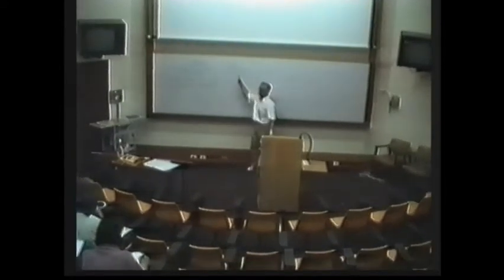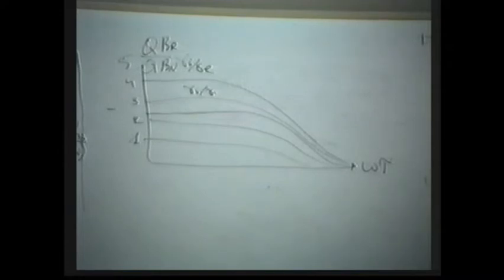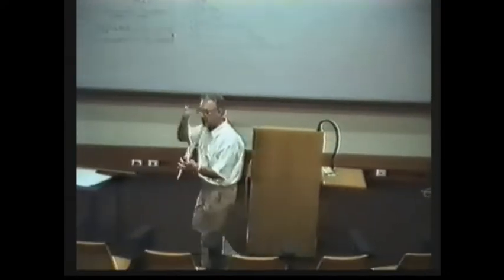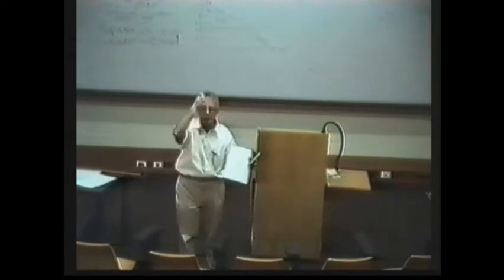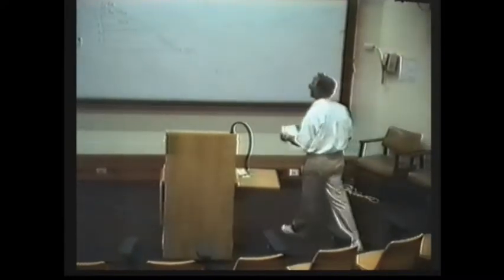So first of all, I hope it's clear that when we are at the low frequency part of the spectrum, current inside of the conductor, current outside of the conductor is defined mainly by what? Primary electrical field. That's the physics. Because at the low frequency part of the spectrum, the induction current is relatively small, and the primary electrical field plays the dominant role.